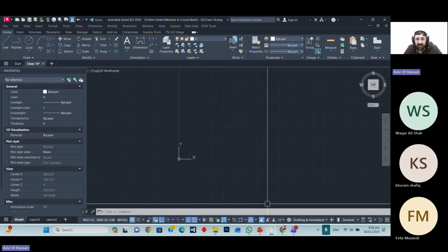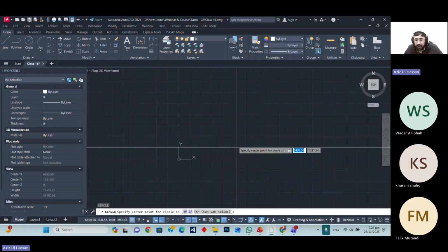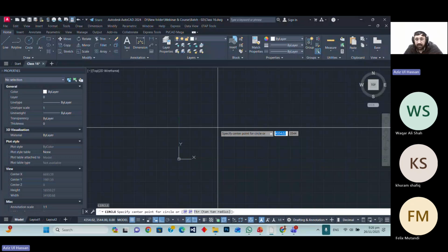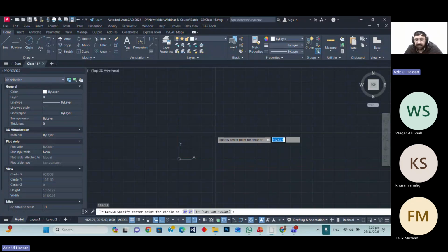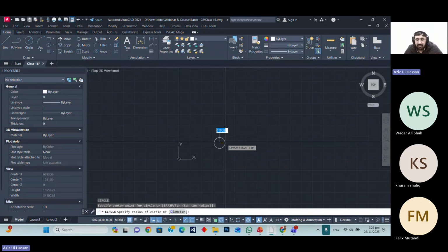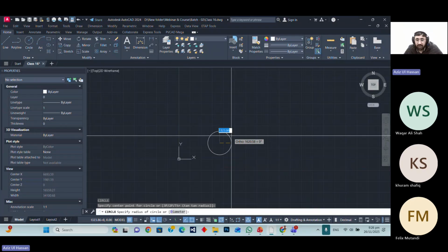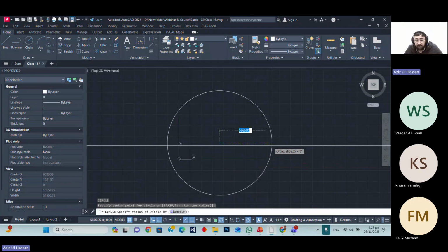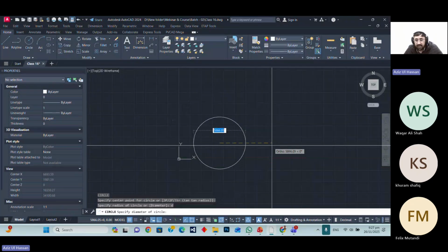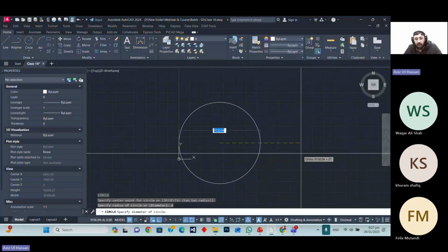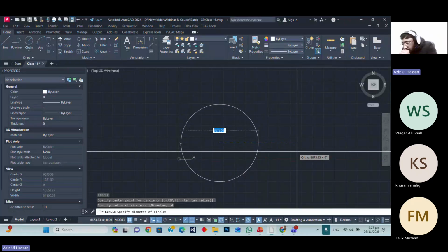Now, if you want to make a circle, just press the C command and specify the center point of the circle. It asks you to specify the center, where you just click. Like here, I have clicked, and now it asks me for the radius. You can see it is showing this length; this should be the radius. If you press D, now you can see it asks me for the diameter of that circle.